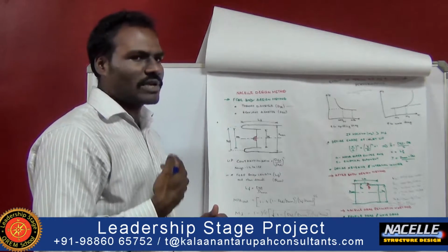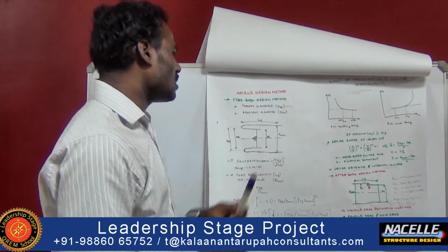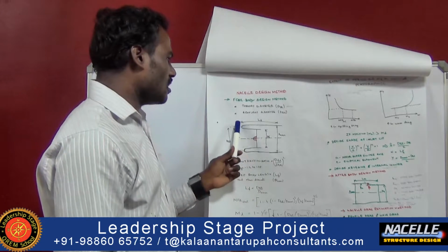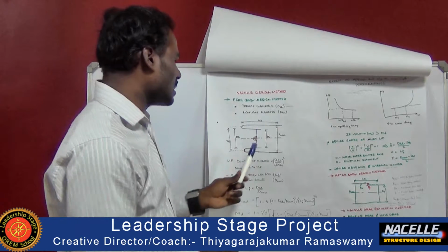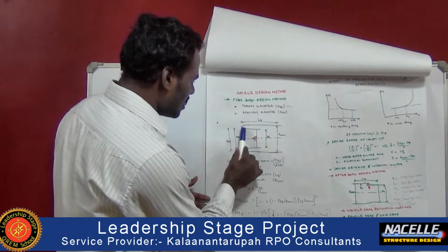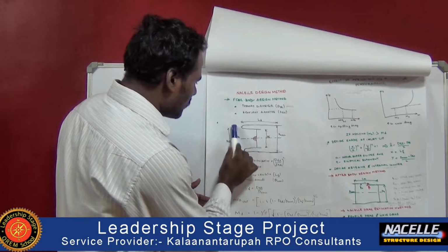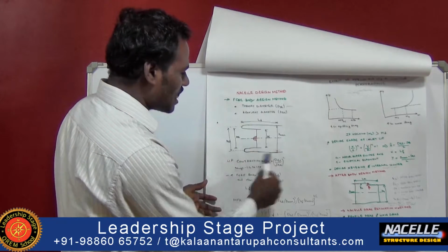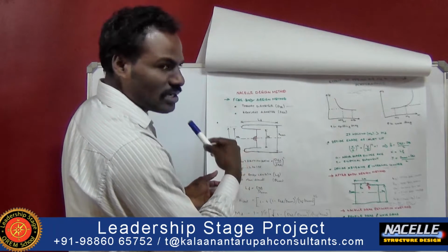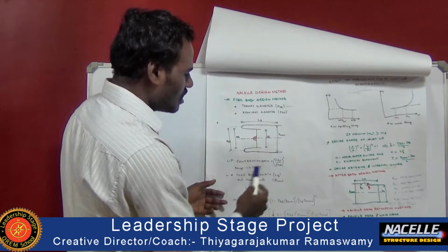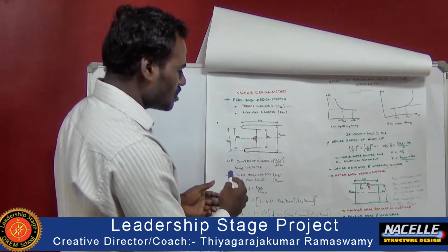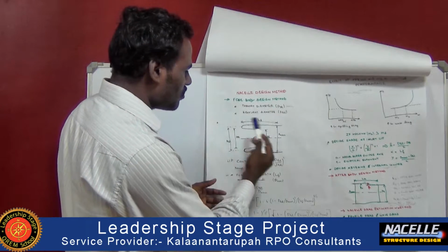Based on the Mach number, we can calculate the throat diameter of the nacelle, and with respect to the throat diameter, we can calculate the highlight diameter. This graphical representation of a nacelle shows the dimensions calculated with respect to the forebody diagram.